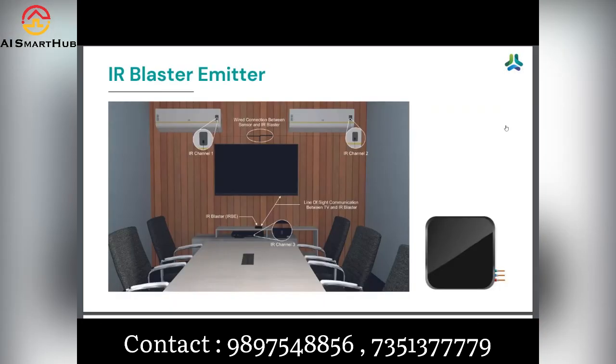In the second model, you can see that IRBE includes an IR blaster and 3 wired emitters. Here we can control an appliance in another room by stretching a wire from the IRBE to the appliances. The command will pass through the cable to the appliances. We can connect 3 different appliances by extending a wire. We recommend using a Cat6 cable up to a length of 100 meters.